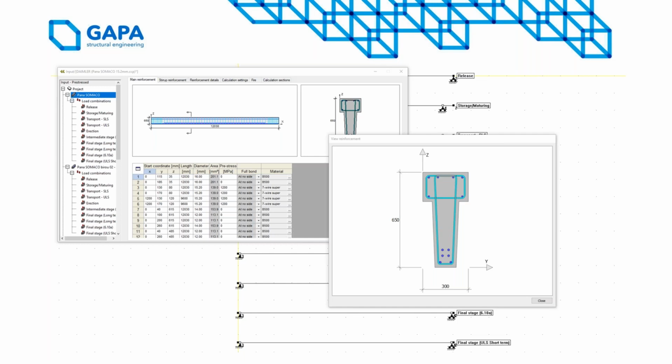As Flavio mentioned previously, we use some debond in the length at the beginning and the ends of the strands. In this case, I had a 1.2 meter debonded length on the second layer, so on these strands here. And you can see that also in the purlin elevation. You can see that they don't start from the beginning, but they start from some distance away from the end.